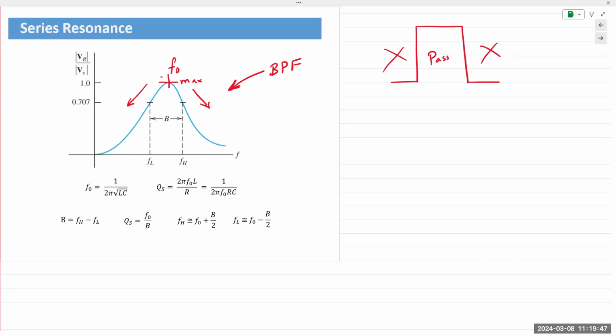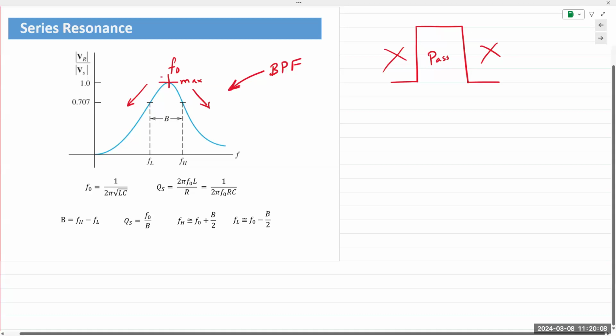And because this is a band pass, meaning there's a band of frequencies, there are 2 cutoff frequencies, but the principle remains the same. You find the value where the power drops to 50% of the input power. Everything above is passed, everything outside is cut off or blocked.